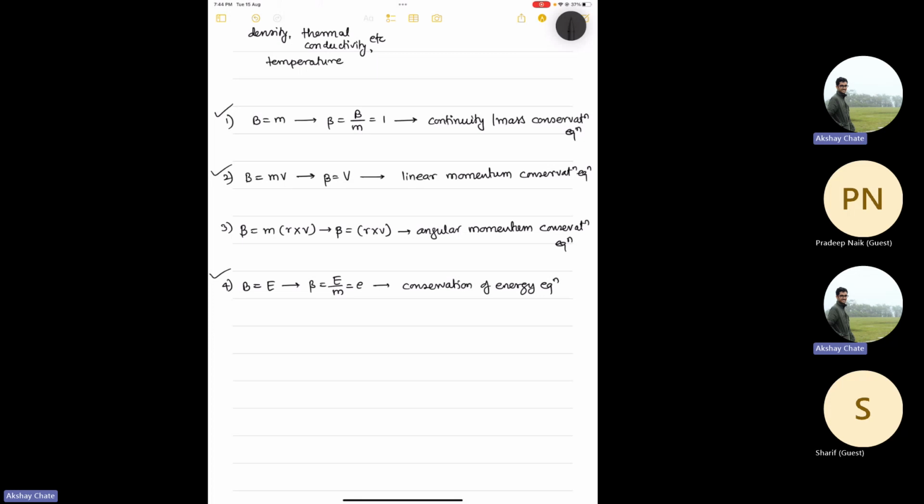And in the same experiment, if somebody is doing it with, let's say, 100 kg of water, their heat requirement will be exactly 10 times that of mine. So it is very difficult to do comparison when you are reporting extensive properties. But if you are reporting intensive properties such as temperature, pressure, then anybody can compare those with their work.